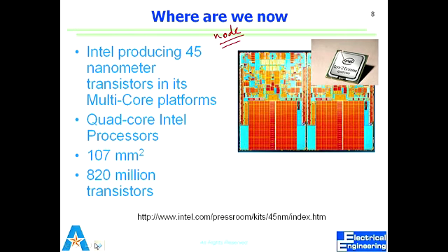There is something we use to define what kind of technology we are using. When I say technology, it's depicted in terms of nanometers. So 45 nanometer technology, 65 nanometer, or 22 nanometer. When somebody says we are at the 22 nanometer node, it means that the industry or the production has the capability of producing a 22 nanometer channel. Channel is something which defines how far apart our source and drain are.